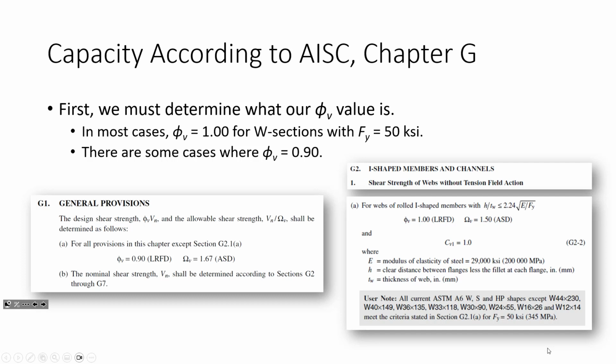But what we do is we take a look at an I-shaped cross-section, and what we're interested in is sort of two parameters. So we have this term H. H is different than the depth because H is accounting for those little rounded bevels that you get right there. And so what we're interested in is web slenderness, and then we're interested in what's called flange slenderness. The reason for the two is because we're only interested in half of the flange.